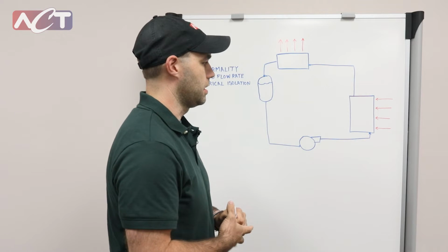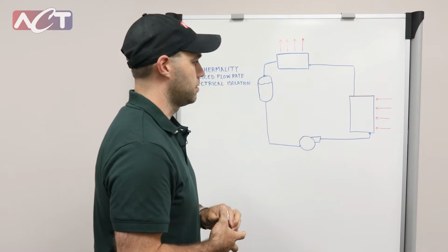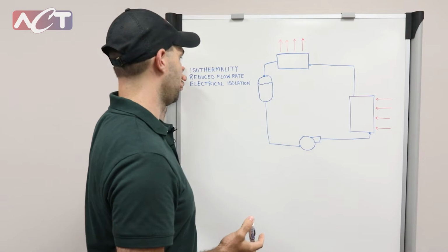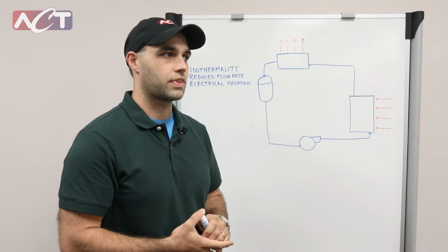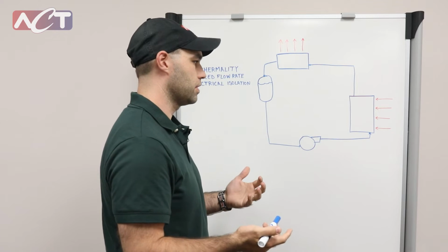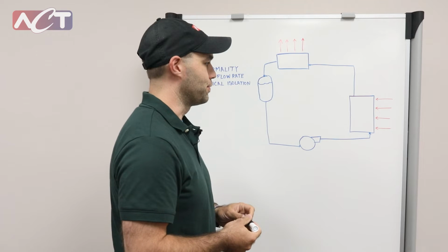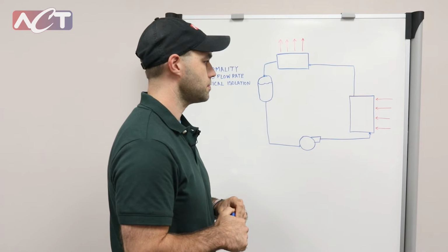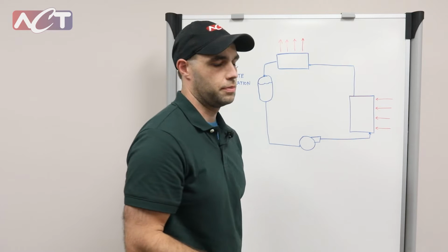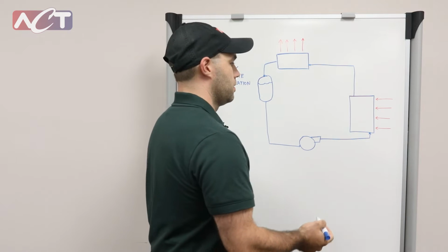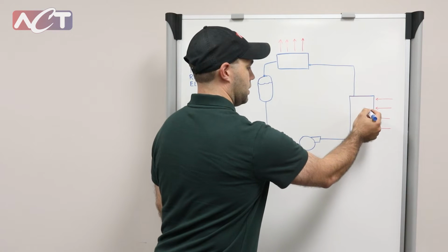The main advantages of the two-phase loop come from several things. So one advantage is isothermality. That comes from the fact that you're boiling the water, it's not water, it's coolant, as it goes through the evaporator. So the evaporator would typically be like a cold plate with some sort of devices on it that you're trying to cool.